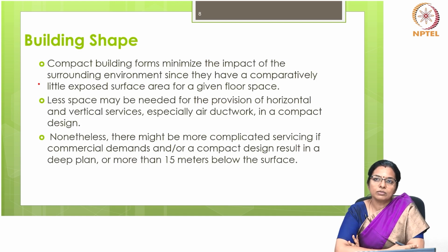Compact building forms minimize the impact of the surrounding environment since they have a comparatively small exposed surface area for a given floor space. Less space may be needed for the provision of horizontal and vertical services, especially air ductwork, in a compact design. Nevertheless, there might be more complicated servicing if commercial demands or a compact design result in a deep plan of more than 15 meters.